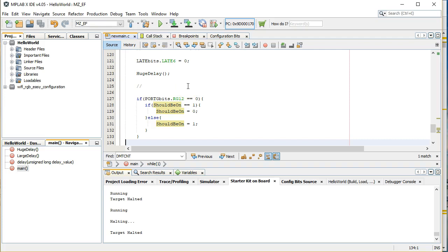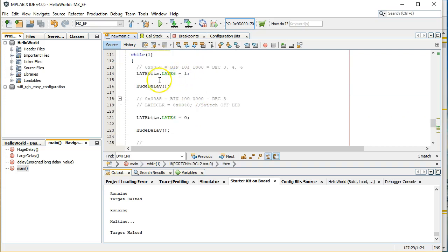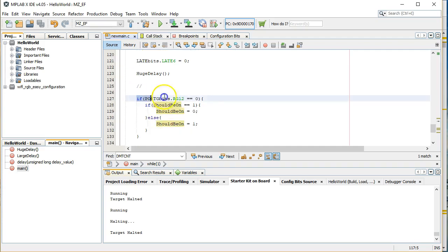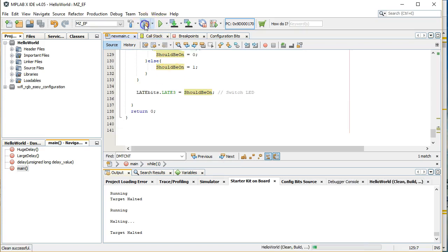Because you need to have it held down through one cycle, because it's only going to read it specifically right here. So if you have it held down from the start of this to the end of this, and then you let it up, then it's not going to find that it was called. So you just want to make sure that you understand how this works, so that you know how long you need to hold the button down in order for it to correctly operate.